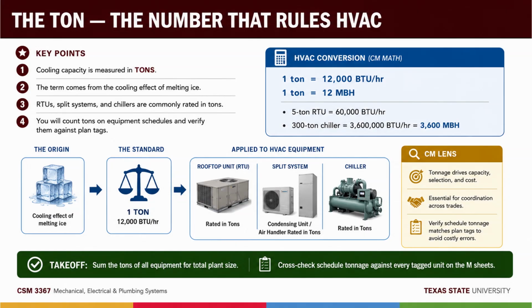And remember the relationship you already know. U is the reciprocal of R. U equals 1 over R. R-value measures resistance to heat flow. Bigger is better. That's the number on the insulation bag. U measures how much gets through, smaller is better. An R20 wall has a U of 1 over 20, 0.05.